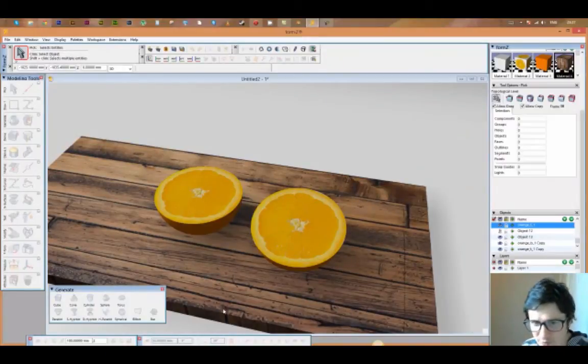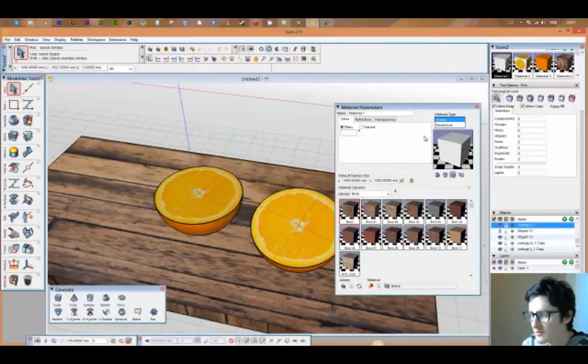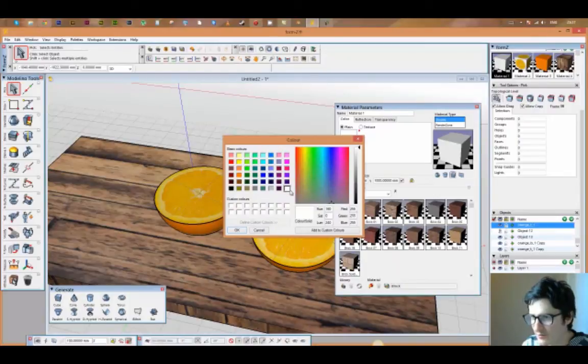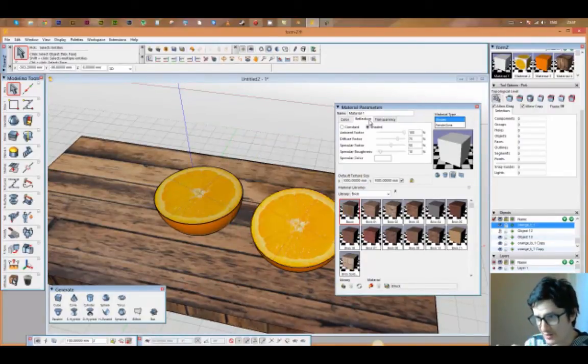And you can see now that our wood comes through with these nice looking scratches and marks and grooves, and it's just looking more like wood. Final thing I'm going to do is adjust my background gray material. It should be white, but we can make a couple of little adjustments to make it a little bit more white. So make sure the color is white, that's okay. And in reflection, let's change the diffuse factor to much higher, and specular factor down a lot more. And that should give us a much more white material.